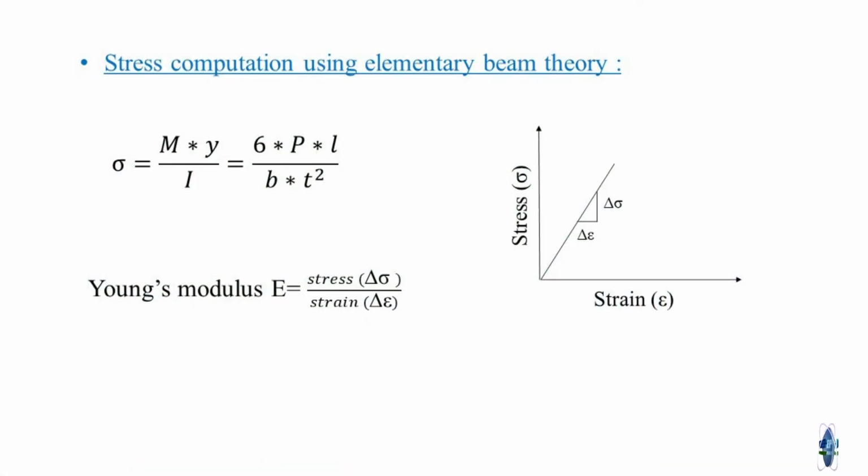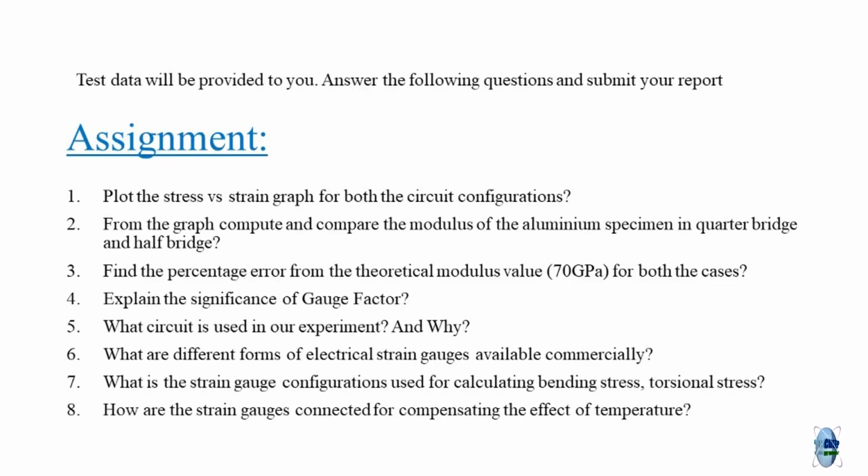I will be providing you the load and corresponding strain data. Stress can be computed using elementary beam theory. So, bending stress can be computed using the formula mentioned here. Plot stress versus strain and find the modulus using the slope. So, you need to solve this assignment and submit your report.